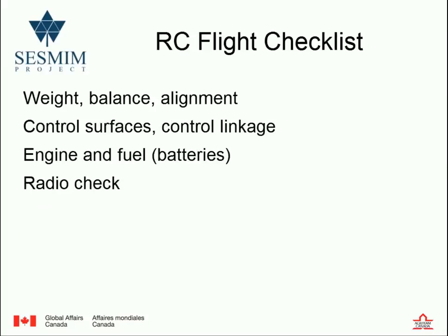Yeah. Okay, so in terms of the flight checklist, things we need to worry about, even more so on a quadcopter, you're worried about the weight, the balance, the alignment, and control surfaces and control linkage. Gary will show you that with a tough wing. We'll talk about that a little bit. A lot of this is less of an issue with the drone, the quadcopter. So what you do have to worry about on the quadcopter or the DJI is that the propellers are not too damaged by the operator.